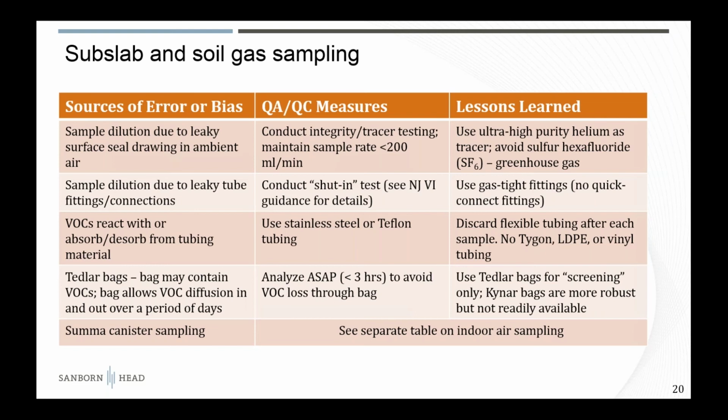Which brings us to Tedlar bags, and you want to be careful using these because they may contain VOCs just by dint of how they are manufactured, and they also allow VOCs to diffuse in and out of them. So if you're going to use them, you probably want to use them with an on-site laboratory, have that capability to analyze them as quickly as possible. These are not typically sampled and then sent off to a lab for analysis because the potential loss of accuracy is pretty high.